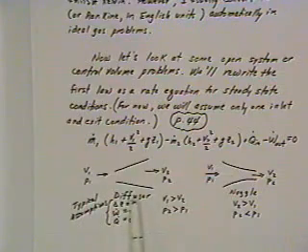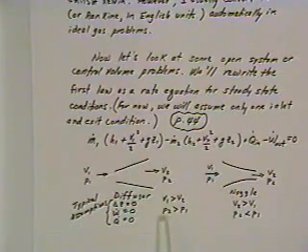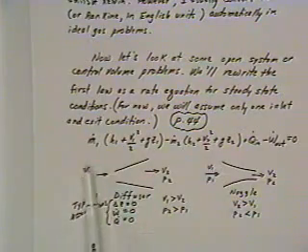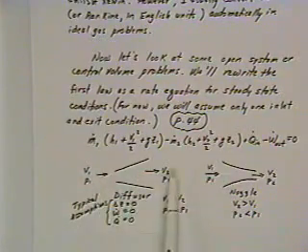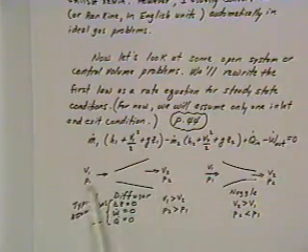And of course, in the case of a diffuser, your interest is in slowing down the velocity of the fluid or increasing the pressure, whichever way you want to say it. So what happens in the case of a diffuser is that with an entering velocity and entering pressure, V1 and P1, V2 is less than V1 and P2 is greater than P1.